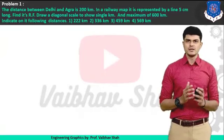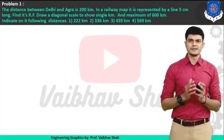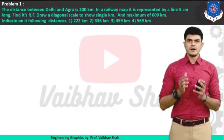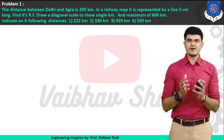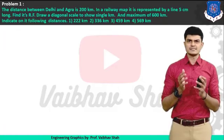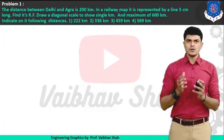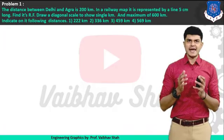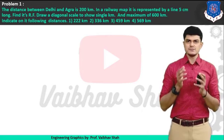Problem number 1. The distance between Delhi and Agra is 200 kilometers. In a railway map, it is represented by a line of 5 centimeters long. First, find out its RF and draw the diagonal scale to show single kilometers and a maximum of 600 kilometers.